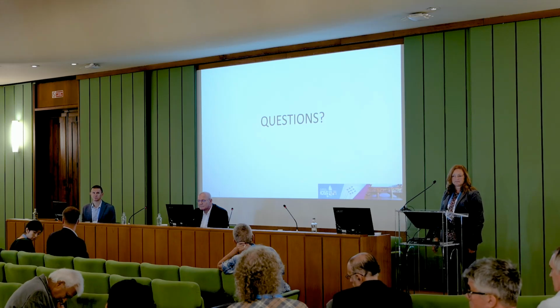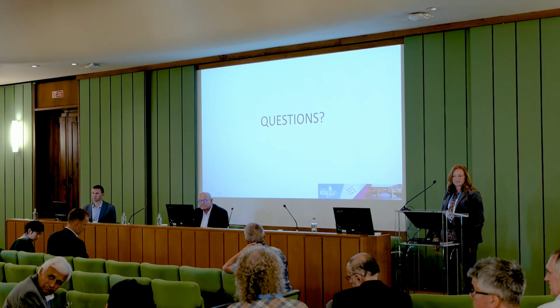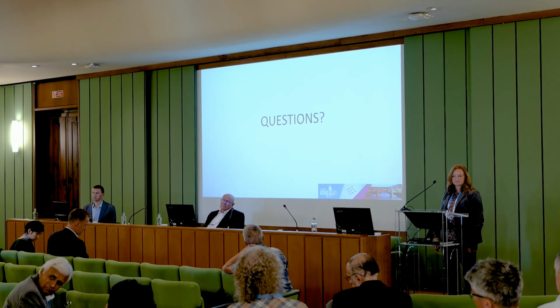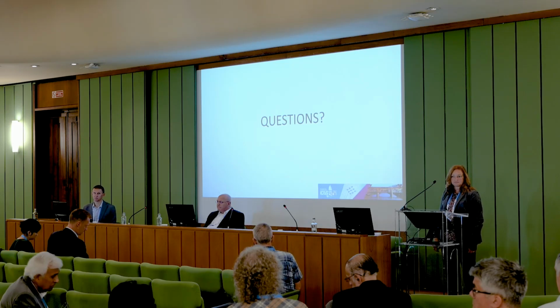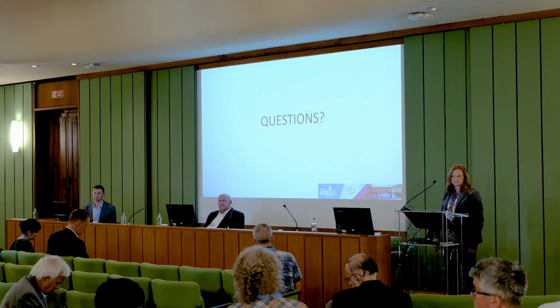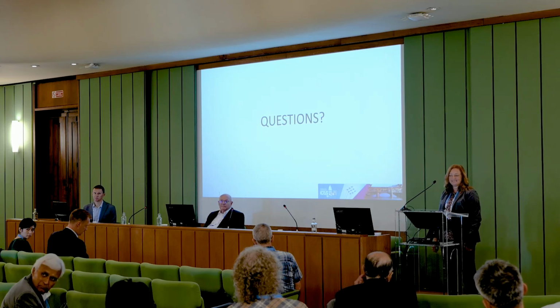But what is quite interesting is that you've mentioned that we've checked the geometry and all that. But personally, I think it's the flow which is different, because if you look at the slope of your lift at very low incidence, I would expect it to be sort of linear, assuming that you haven't reached a condition where you can start having separation, or what we call low-speed buffet. And you can already see that there's a bit of a change in slope. So I think that the devil is in the detail, which is the flow measurement, the characterization of the flow. Well, that's my personal comment, it's not really a question.